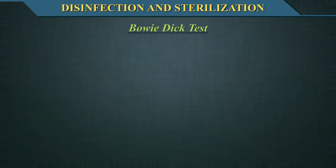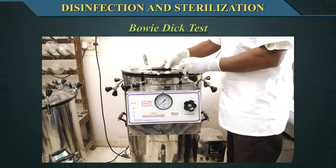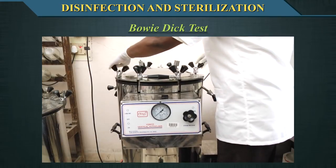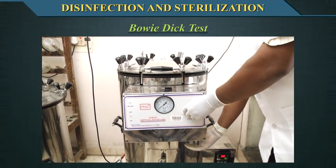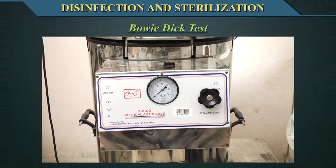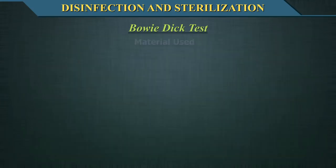Bowie-Dick test. It demonstrates even and rapid penetration of steam in a steam sterilizer or autoclave. If air and non-condensable gases are not removed from the chamber and the load or from the steam supply, they may become trapped within the load. This would prevent penetration of that part of the load by steam and consequently, sterilizing conditions may not be obtained. Materials used.